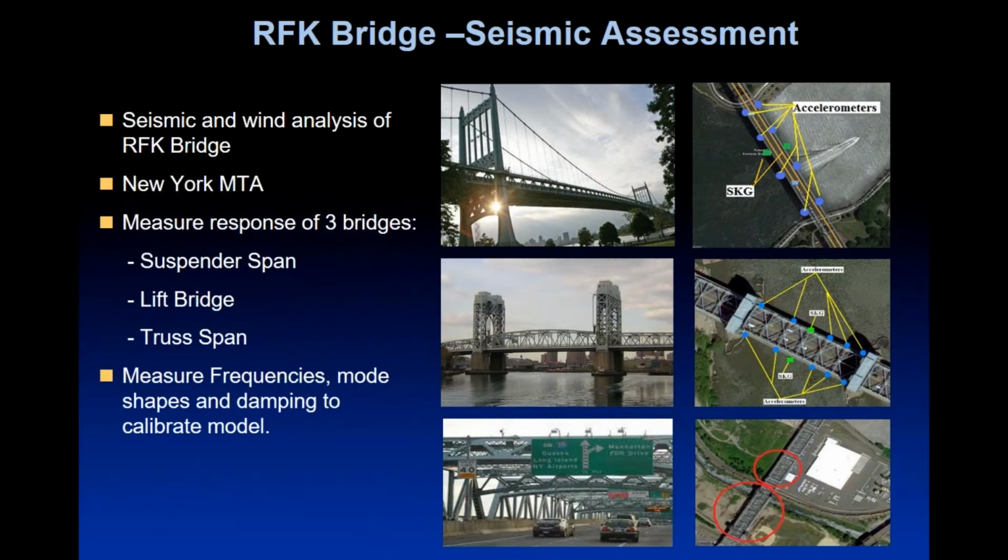We looked at big bridges. We've looked at the Manhattan Bridge and the Triborough Bridge, as it was called. It's now the RFK Bridge. And again, we've found all sorts of things with our ability to measure very, very precisely and down at low amplitude. What we've got here is aerodynamic instabilities that occur on a large span bridge. And a natural period of shaking of the center span of the RFK Bridge of 10 seconds.